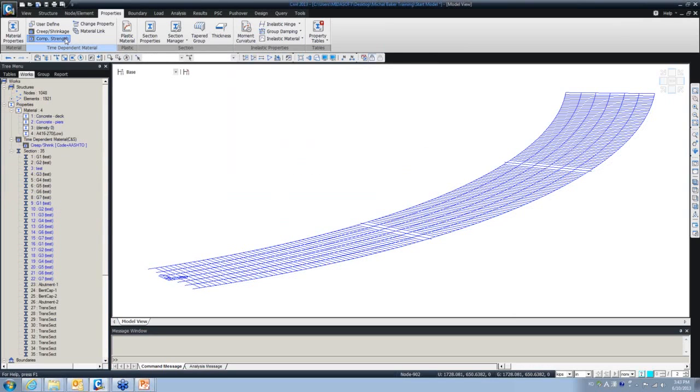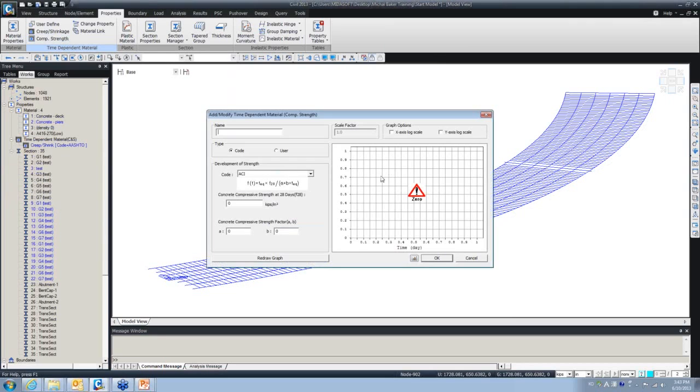And the same way you can define the compressive strength of concrete. The compressive strength of concrete is also important, especially when you have cast-in-place bridges, or a post-tensioning bridge project where you want to monitor the behavior of early age concrete for, let's say, cracks and deformations, because it takes about 4 weeks for the concrete to reach its ultimate strength and be fully loaded.